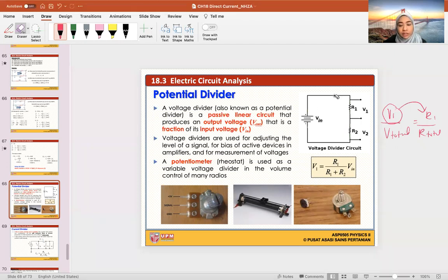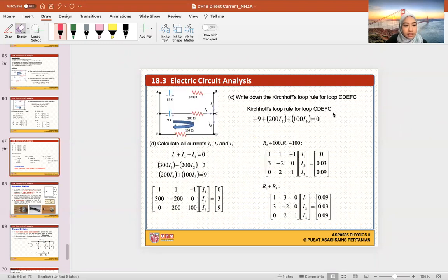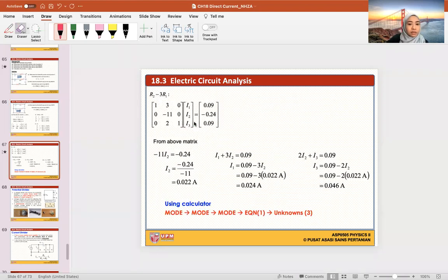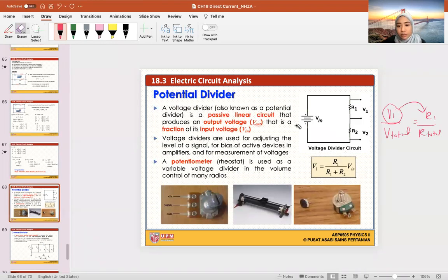Okay, this is for a circuit looking like this. For the circuit looking like this guy, you can't use the potential divider equation, because here you have 2 batteries and we don't know the distribution of the voltages across these resistors. However, for circuits like this guy, where you only have a battery and the battery is divided among resistors, then you can use the potential divider.